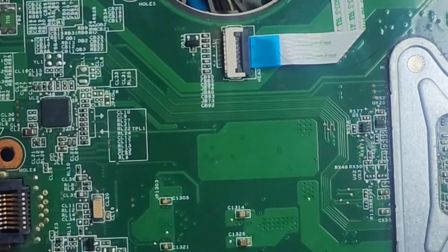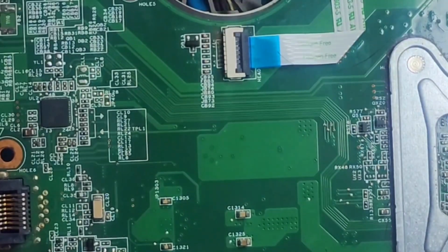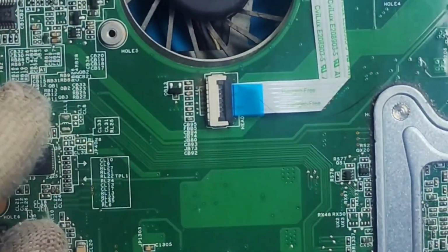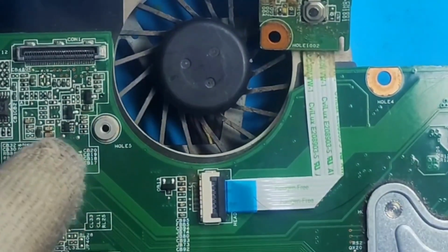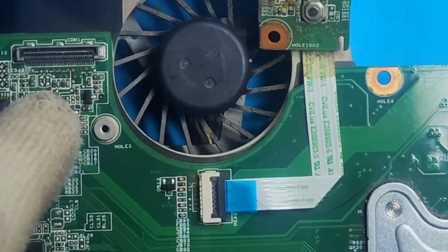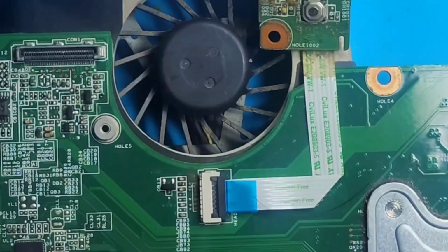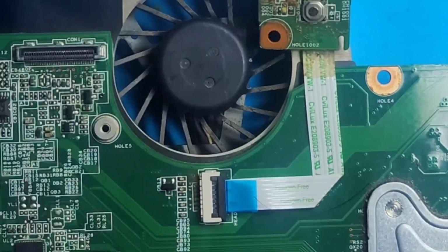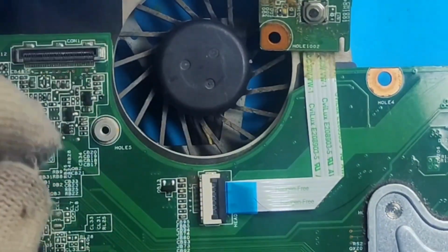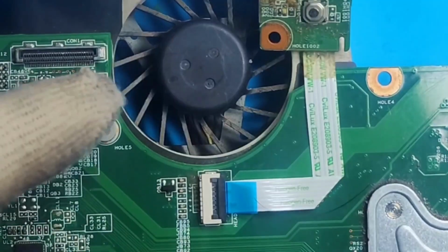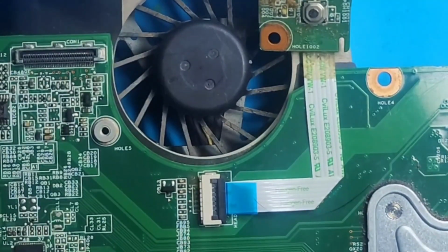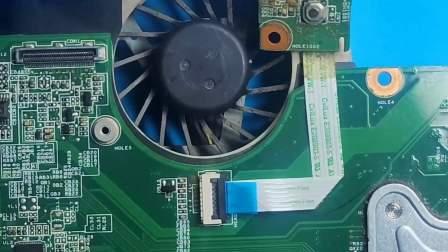So there were two problems. There was a short in the inductor. Sorry, the inductor was missing. So we replaced an inductor, and for the LCD VCC, there was a problem in this circuit because of the PCH that is sending low impedance to this circuit here. That's why we were not getting LCD VCC. So we have bypassed that circuit in order to get 3.3 volt at the LCD connector here, to supply the LCD circuit inside the display.